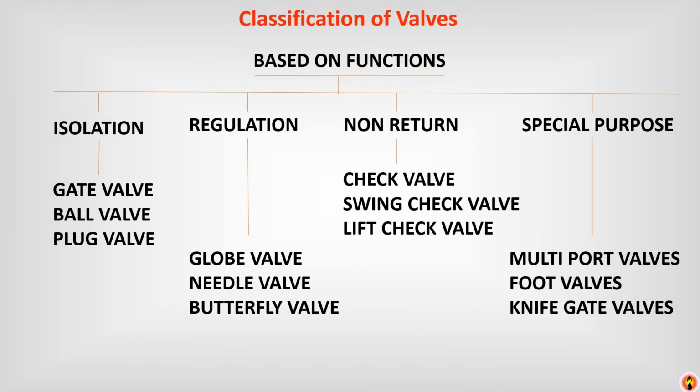Classification of valves based on function: isolation, regulation, non-return, special purpose. In isolation: gate valve, ball valve, plug valve. In regulation: globe valve, needle valve, butterfly valve. In non-return: check valve, swing check valve, lift check valve. In special purpose valves: multi-port valves, foot valve, knife gate valves.